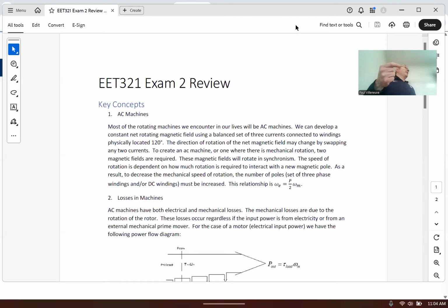So when you're determining the speed of operation, you can take your electrical frequency and convert that from radians per second to RPM. Everybody knows how to do that, right? No? If you're not sure, just always break it down to rads per second. How many revolutions per radian?